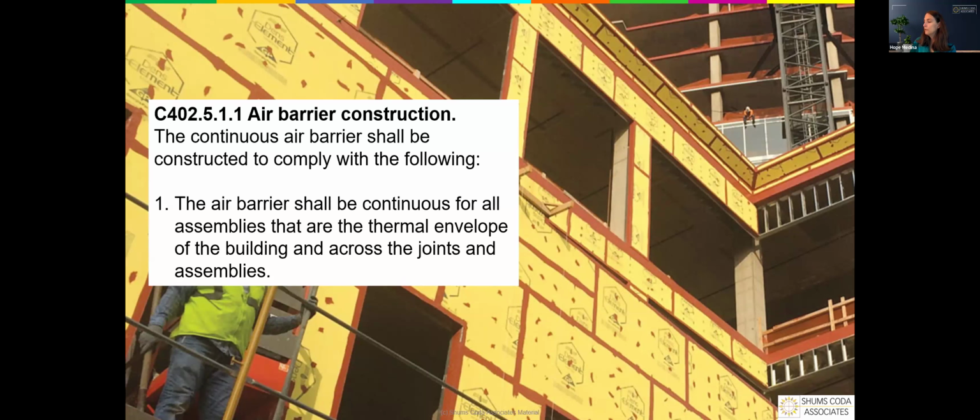Oh, okay. Would the test be prior to drywall installation, or can the drywall be used for part of the assembly? That is an excellent question. I'm gonna partially answer it now, and then you'll probably catch it later. Typically, it's going to be done towards the end of construction, because drywall can be part of the air barrier strategy that can be utilized for a building. So typically, they're going to want that drywall to be installed before they go and do the testing on it. So great question. I like that question.